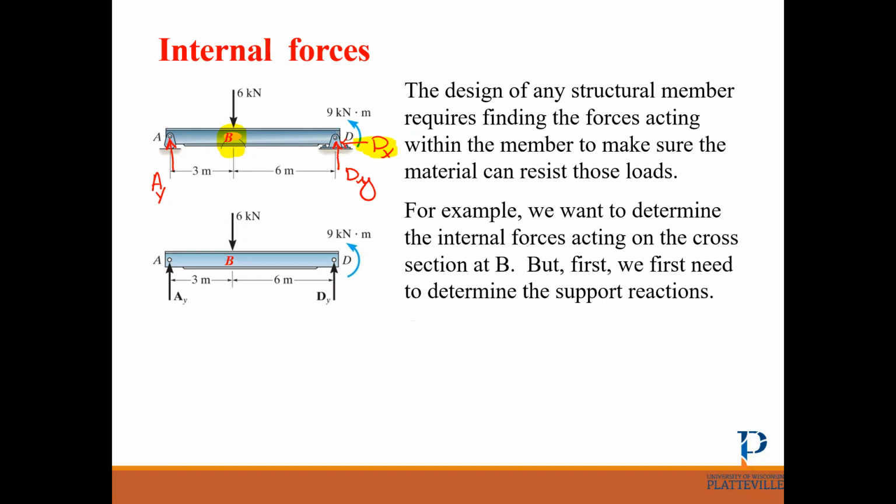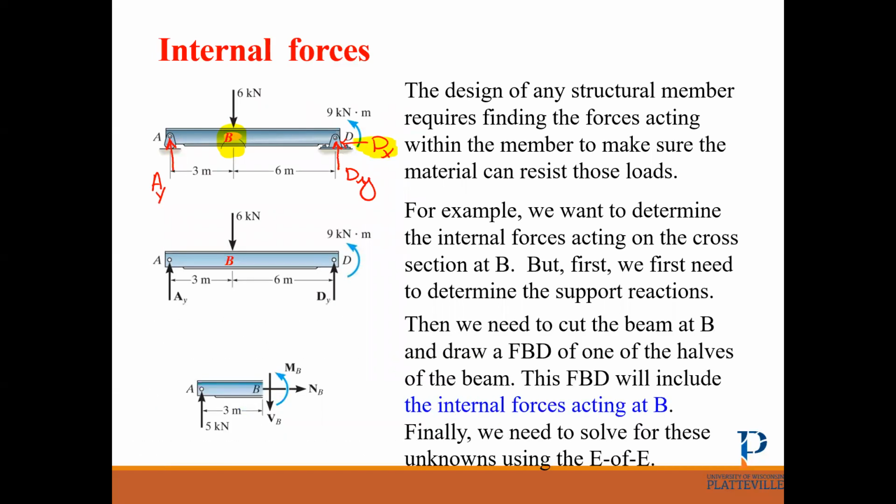The next step is to choose a good cut. The good thing about beams is we don't have to think about where a good cut is. Usually the point where we want to find internal forces is a good cut. After we cut, we call these internal forces acting at B.